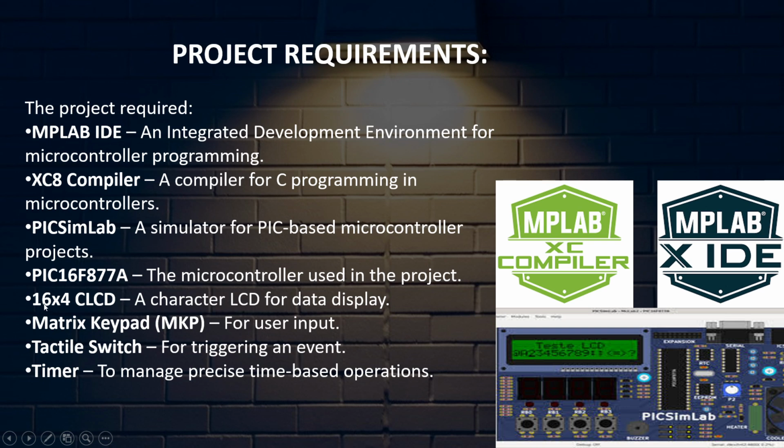And we also have the 16x4 CLCD, which is a character LCD for data display, matrix keypad MKP for user input, tactile switch for triggering an event, and timer to manage precise time-based operations. And these are some of the images of those tools. You can see that this is the XC compiler, and this is MPLAB IDE, and this one below is the PICSimLab.